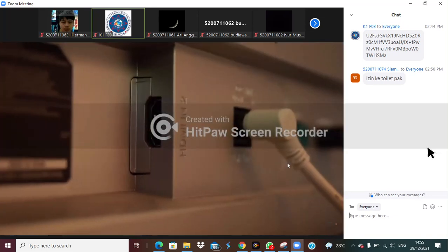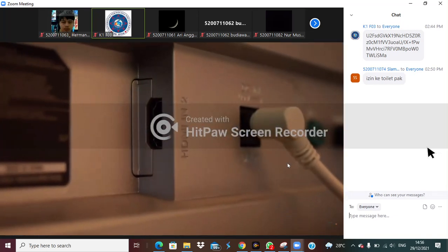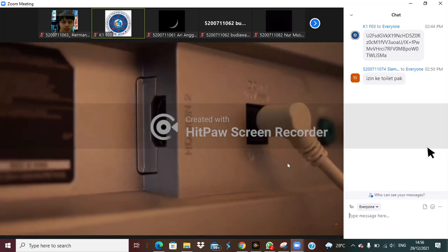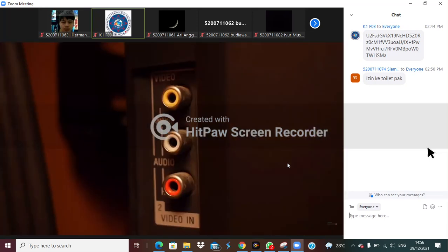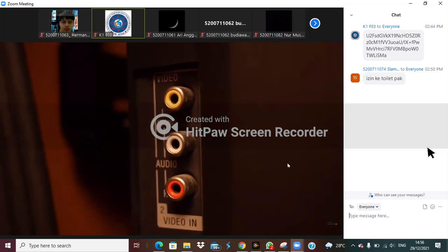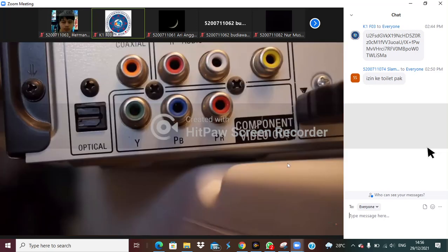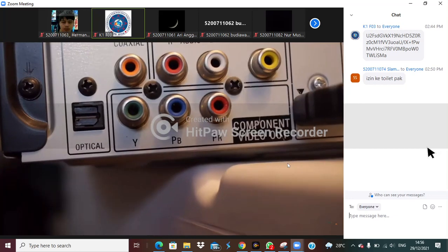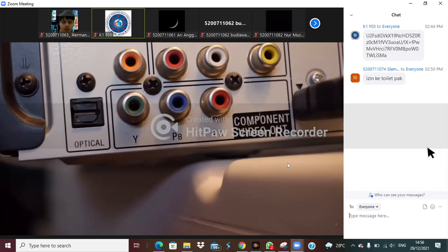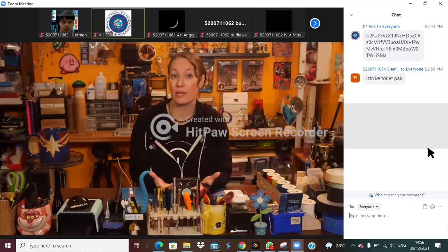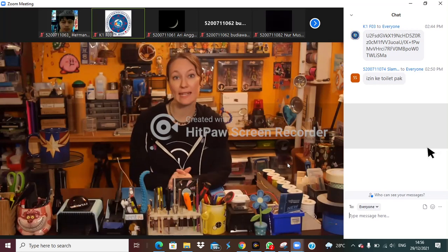DACs are also used for video processing. Many modern TVs and video displays use digital inputs like HDMI that don't require analog conversion. However, on older video displays, you can find RCA jacks with one yellow composite or 3 red, green, and blue component video inputs that are analog. These require the video output device, such as a DVD player, to contain a DAC.